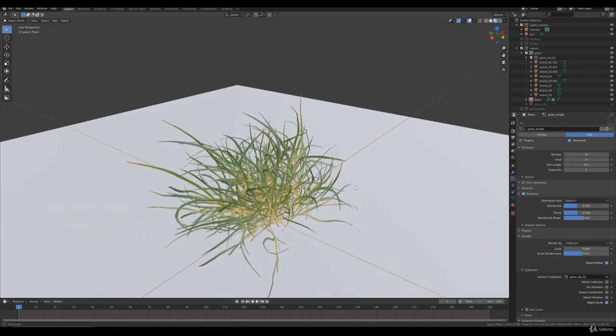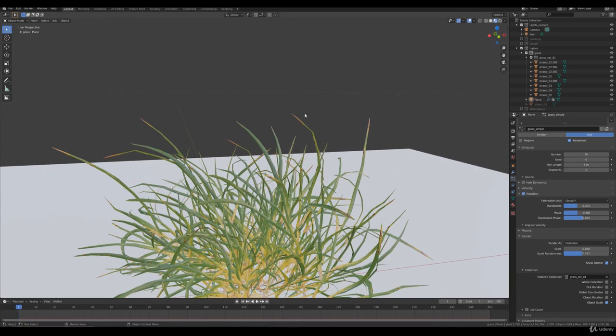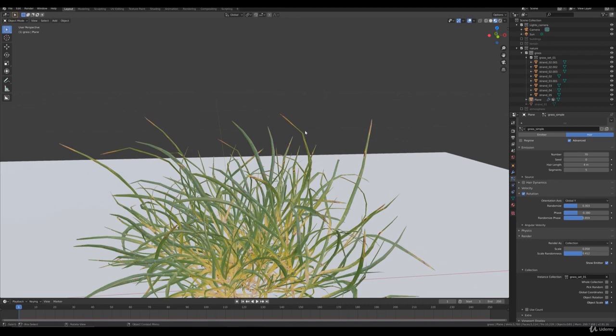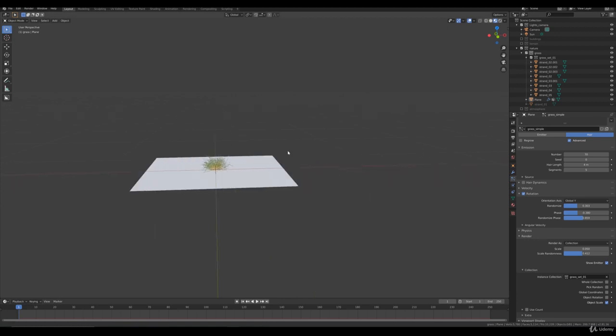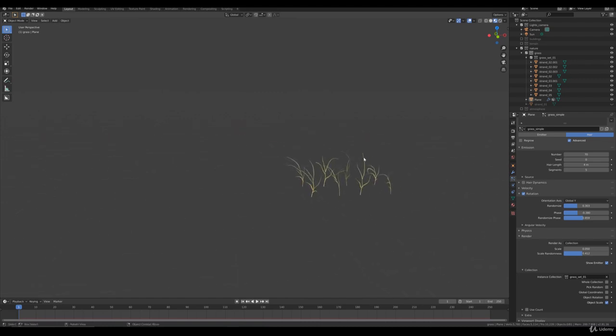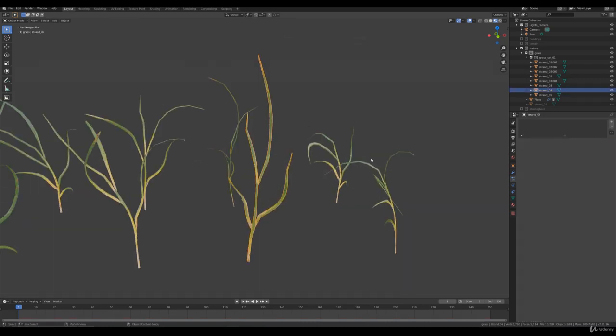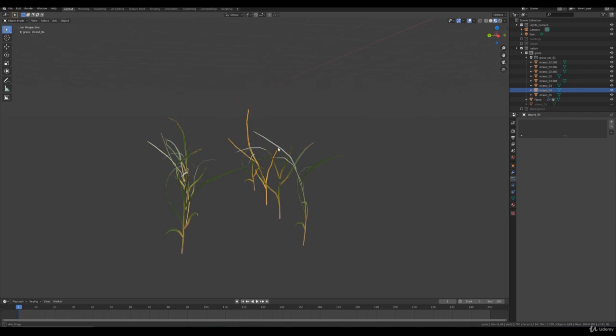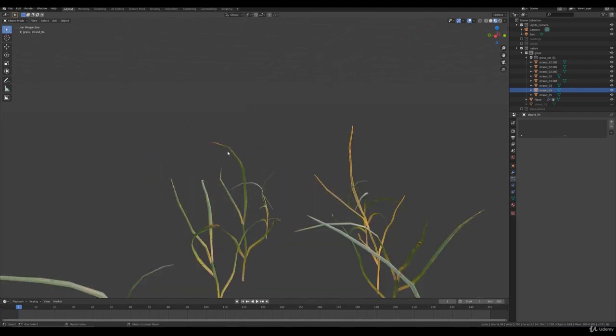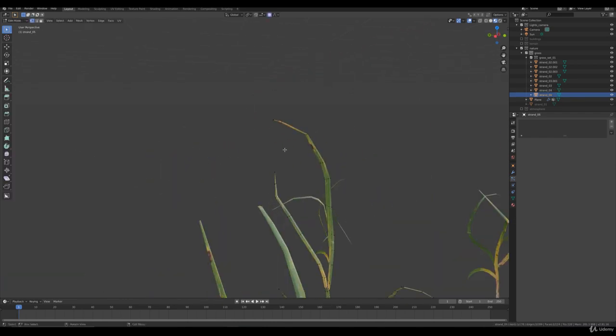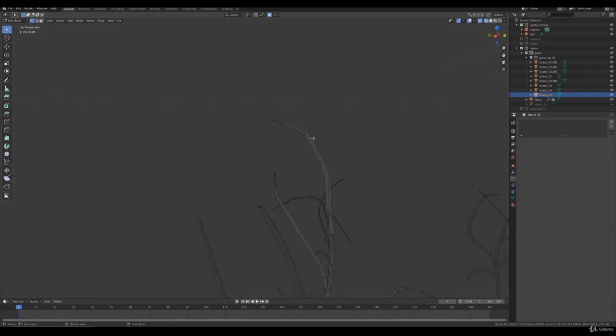All right. Something that is hurting my eyes are these curvy spikes there. So we open the source. It's still opened. And we go to our strands. There they are. Select one control point, so it's in the middle. And we have to find the strand, I think it's that one. So we zoom in, go to the wireframe, and we need to smooth it out a little bit.